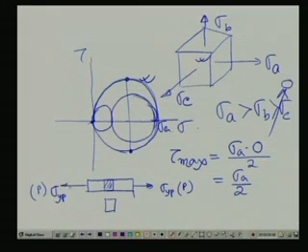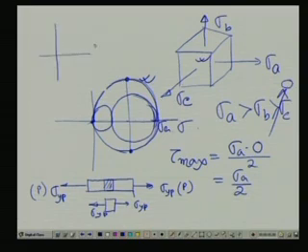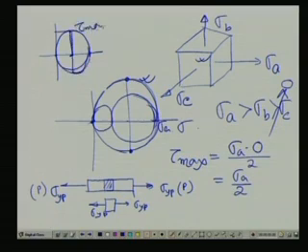You understand, this is the yield point corresponding to a load P. So, the stress element will be sigma yield point, sigma yield point. Then the representation in a Mohr circle is this: sigma yield point, and this is 0. Am I correct? So, this comes out to be tau max.